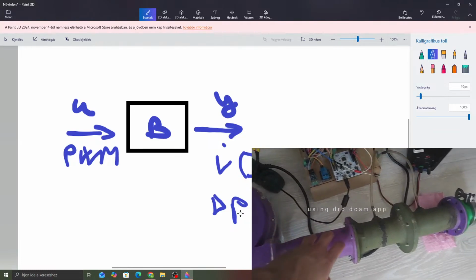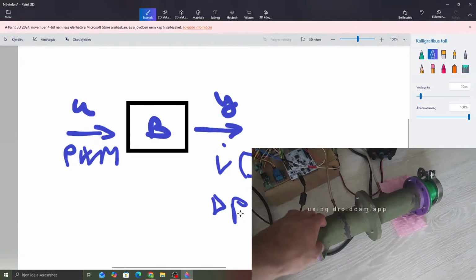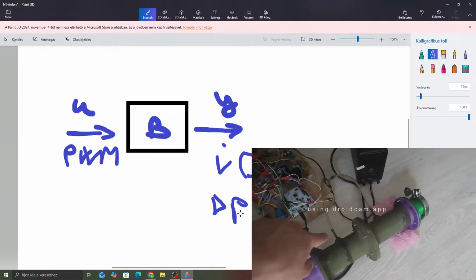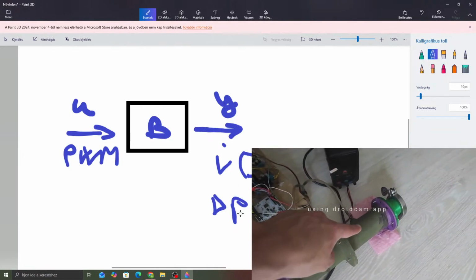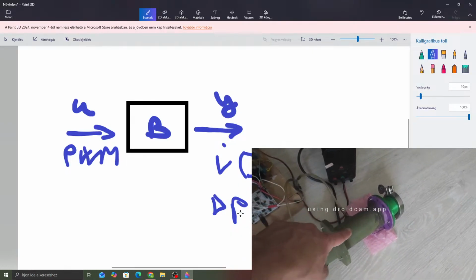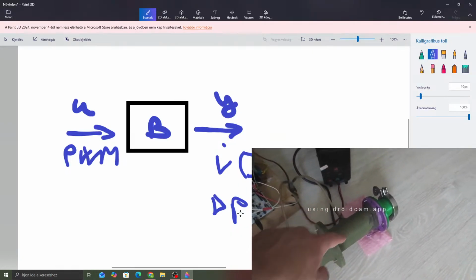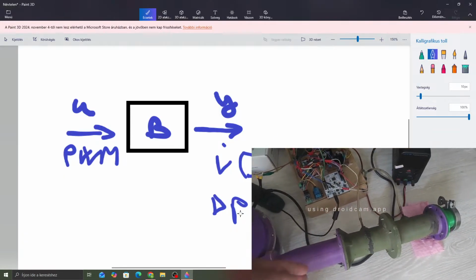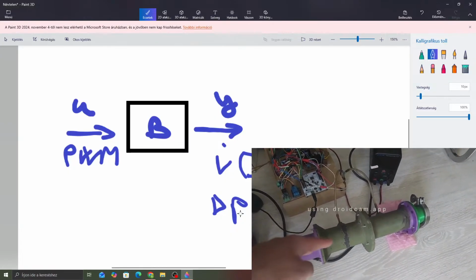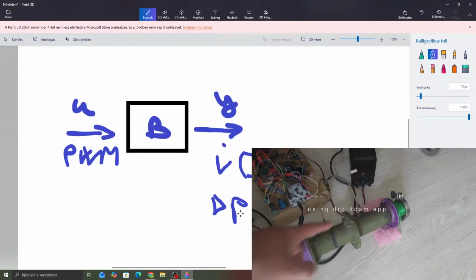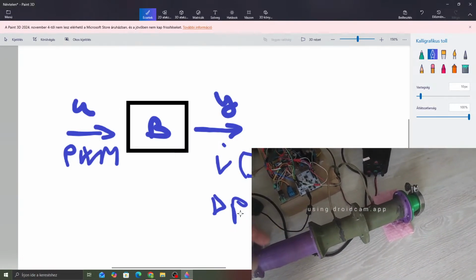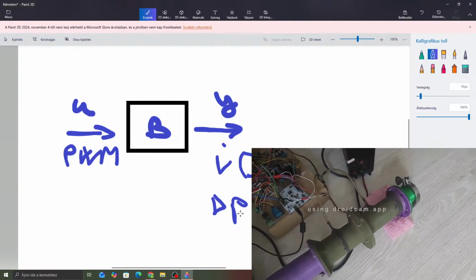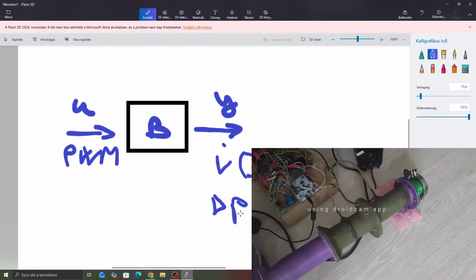Here we have this makeshift 3D printed orifice plate. Basically it works like that. There is differential pressure here: there is a restriction, and there is going to be a pressure drop between here and here. The pressure here is lower than here, proportional to the amount of air that goes through. If 5 liters per second of air goes through, there is 1 amount of pressure drop. If 10, then it is 2. It is linear, if I remember correctly, or quadratic, I can't remember, whatever.